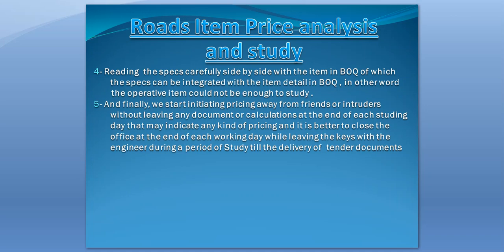Later on, you will discover that according to the specification, this curb should be installed on ordinary concrete of 10 centimeters thickness, and in this case it will be a disaster.